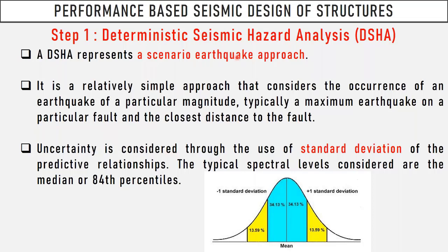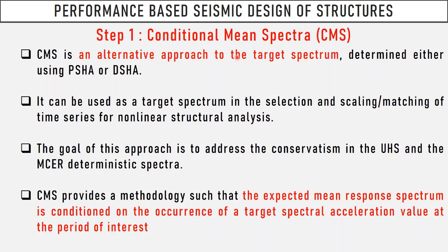You may do that. Or you may have a specific building, and you may need to have the ground motion parameters with the response which is compatible with the response of the building, or in other words, at the response periods of the building that you are going to design, and you are going to make this selection and this scaling based on these criteria.